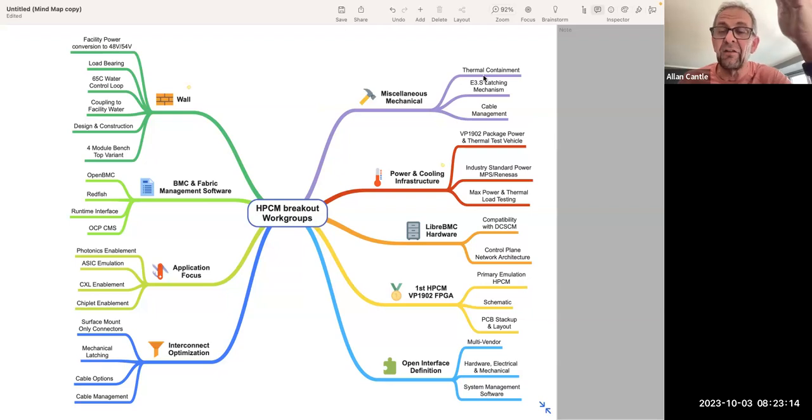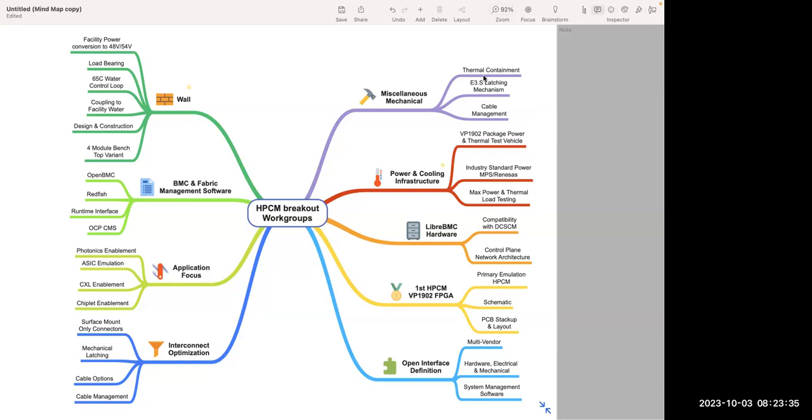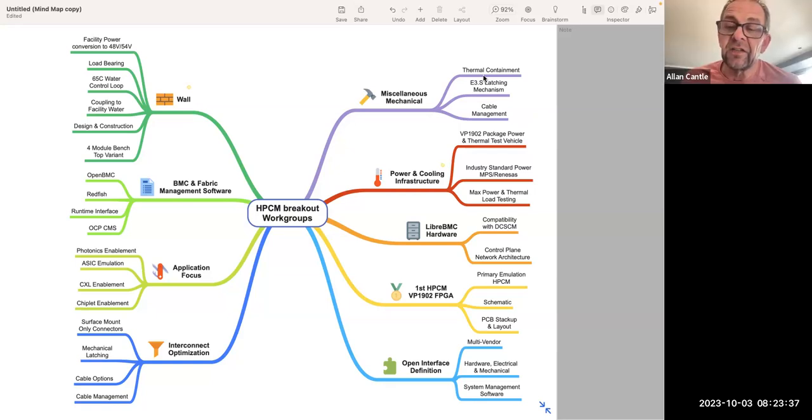the data center itself would be running at around 65 C, and there'll be no humans allowed in there. We may get to that point with a robotic approach in the future, but we're looking at some thermal containment to minimize the amount of leakage, and then you'd still need some level of air conditioning in the data center itself to keep it cool. But we try to minimize the need for a secondary air conditioning in an ideal world. This is the vision of where we want to get to.